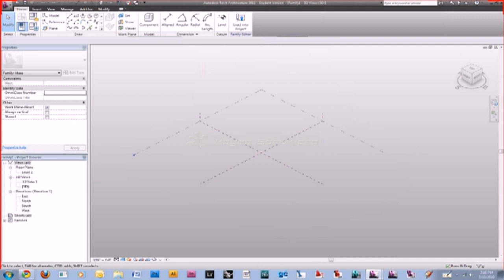I used to not use the conceptual mass tools a lot. I used to just try doing in-place mass, and after this last skyscraper project, it just killed my computer, and my computer is not weak. It killed it because there just wasn't enough behind the in-place massing. So conceptual masses are definitely where you want to go.